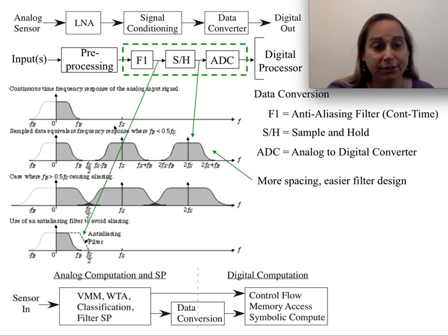Here's what you typically try to do with this filter: you put some sort of block on here that guarantees, even if it is some sort of bandwidth structure, that I can cut it off. And this makes sense. In nice theory, you assume a hard wall filter. The problem is you don't get that. You actually have to build it, and there's some transition region.